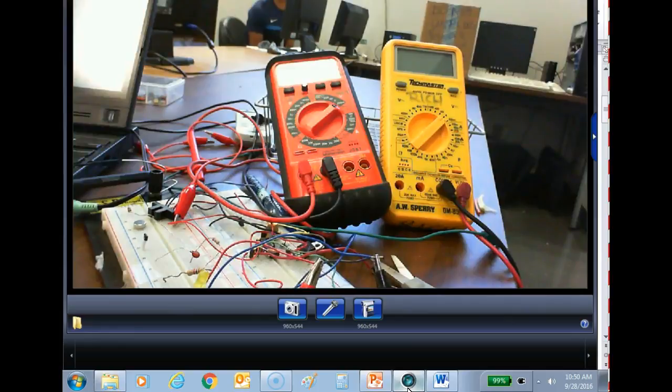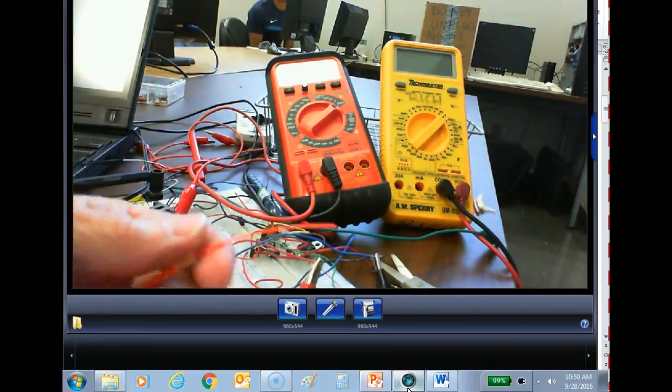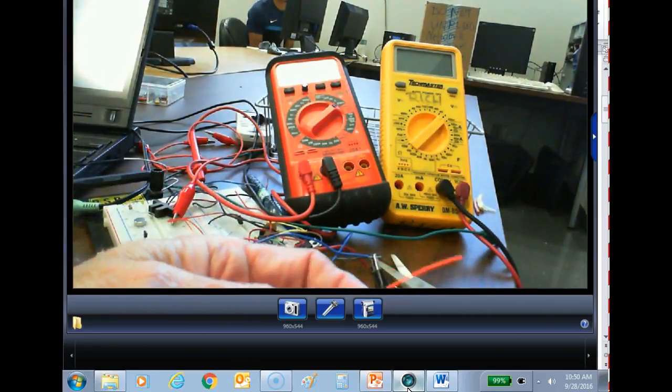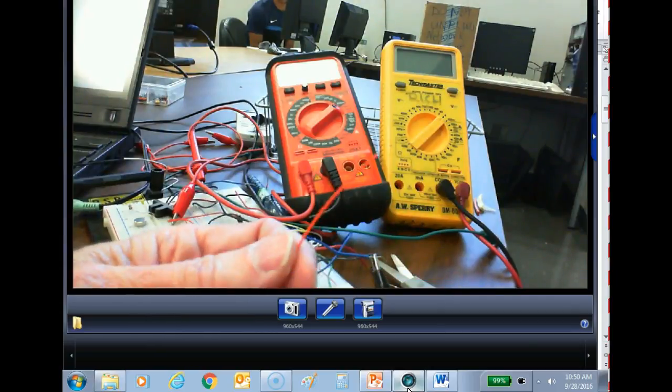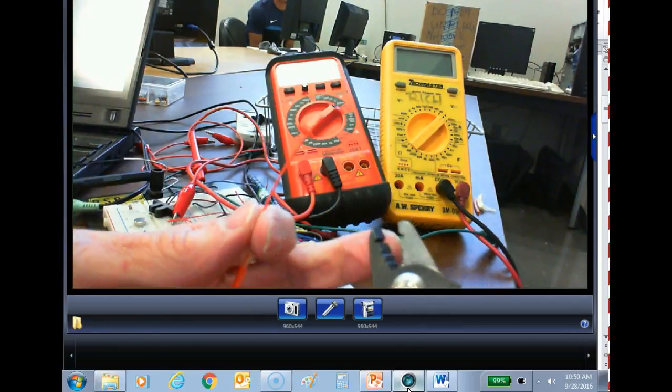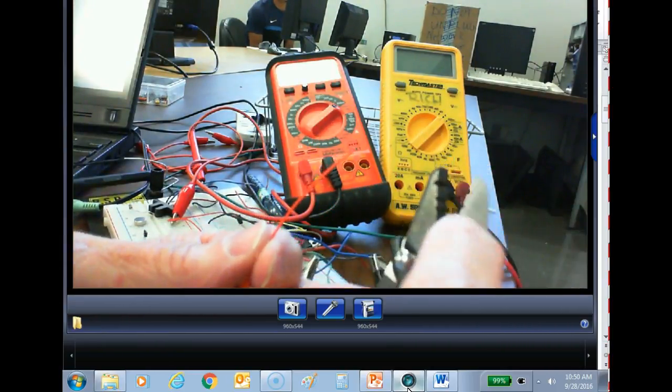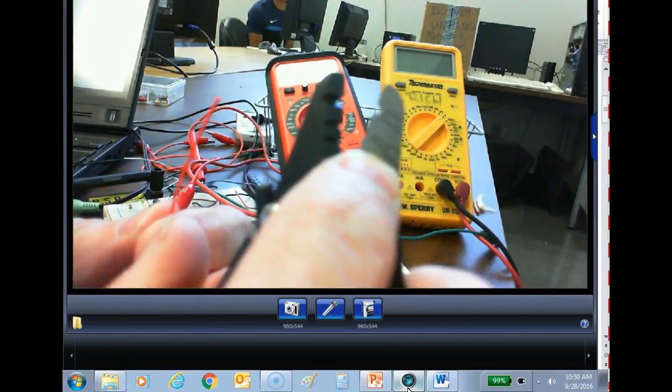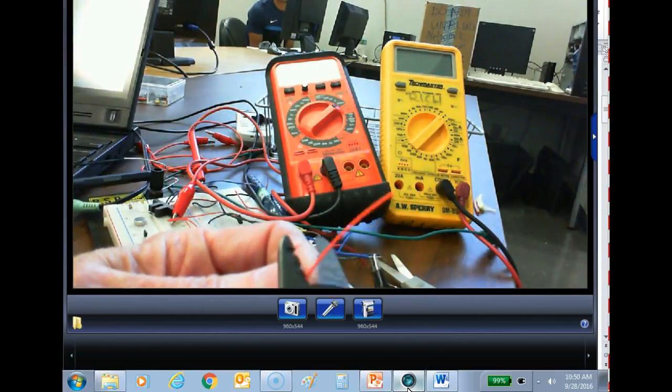And then you'll put this in the scrap bag. I didn't get me a scrap bag. Then you're going to take your conductor. You're going to mark where you want your tight buffer cut at. Then you're going to go down to the next one right here. And then you're going to strip off your tight buffer.